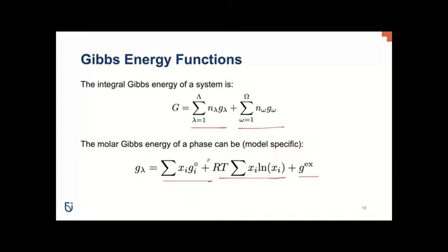This really applies to a single lattice phase. Now the complication comes where the excess Gibbs energy of that phase is handled, which can be highly nonlinear and non-convex. That's where nonlinear optimization is required, in addition to global optimization techniques to handle the non-convexity of these Gibbs energy topologies.